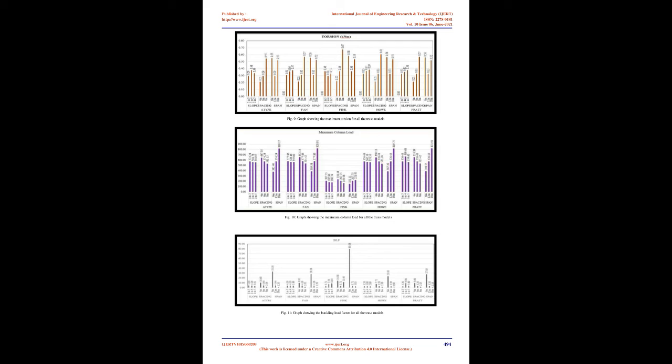Even though the maximum and minimum torsion are experienced at the same slope, that is, 1 in 3, the modifications in slope are associated with notable changes in torsion, and low slope always favored economy in terms of torsion. Torsion suffered a reduction pattern on decreasing the spacing, disclosing spacing as the most interpreting parameter for torsion. Overall, almost all types of trusses showed satisfactory results in minimum torsion except for Fink truss.